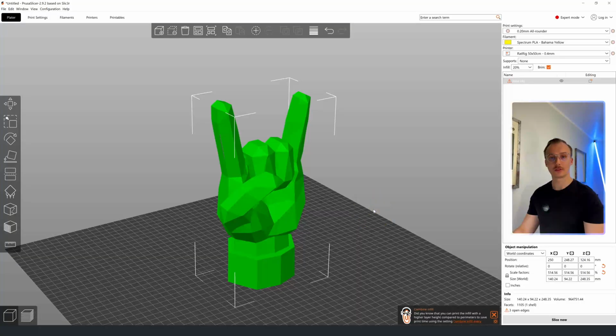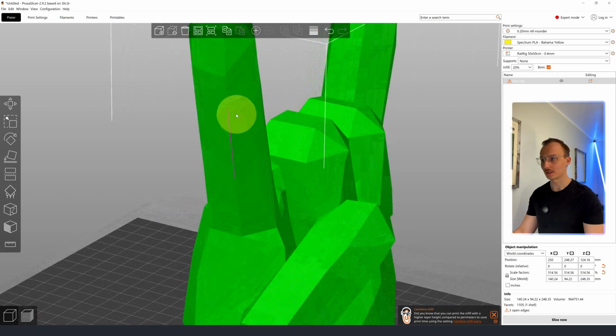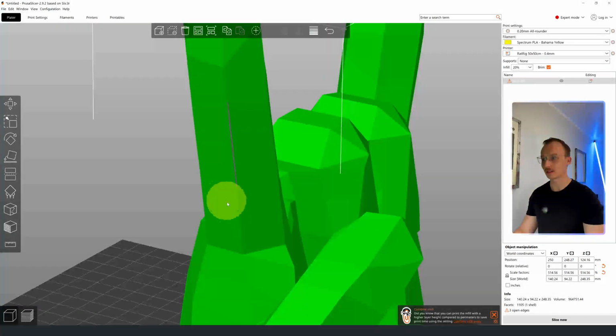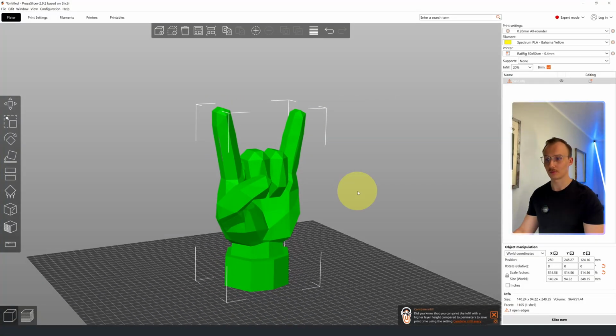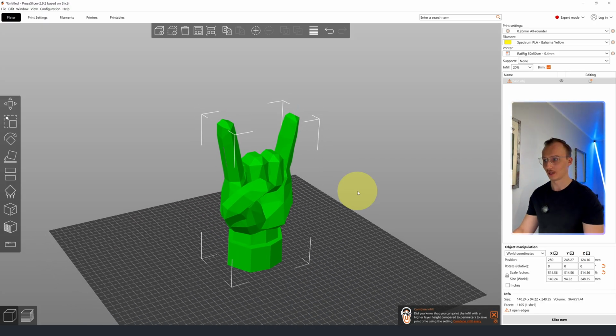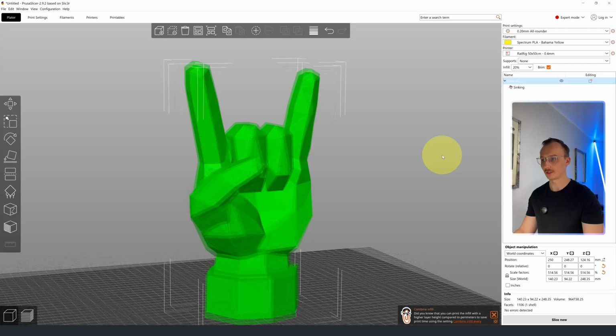One additional thing to keep in mind is that AI generated 3D models usually have more problems than the surface only. In this case, I see this purple line, which indicates that this model is not closed. And this program, PrusaSlicer or Bambu Studio, is perfectly suited to repairing those models. So you get two things at a time. To do that, you just click this exclamation mark. It will run the algorithm and fix the model, and it will be perfectly printable.